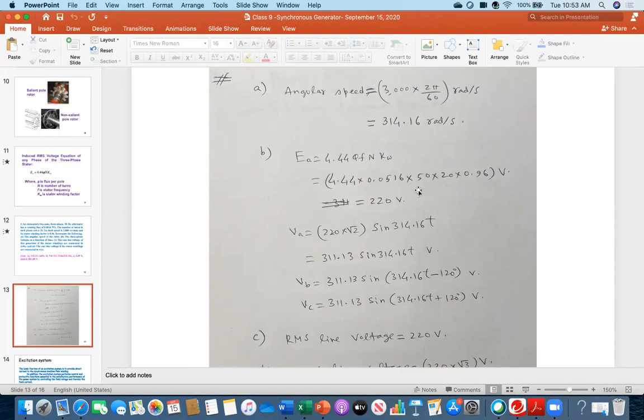Great. So the only thing you remember is this equation, and keep in mind this is the RMS equation and this is for any of the phases. And because to express VA, VB, VC you need the VM, which is the amplitude or magnitude, I just converted the RMS value into the magnitude from the AC circuit knowledge that you have learned.